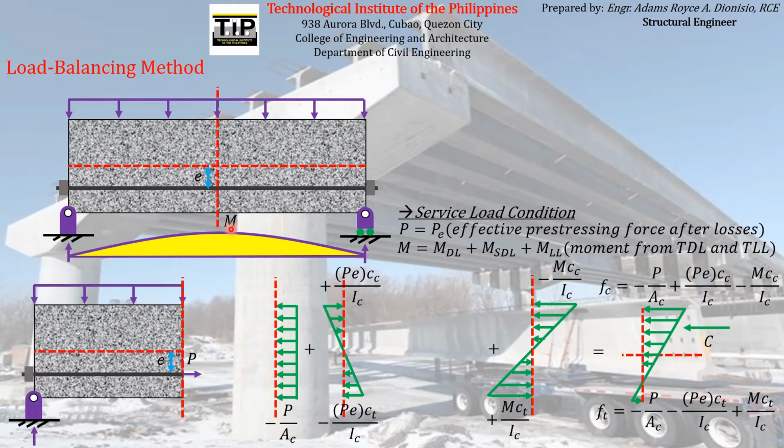This bending moment you see here is the maximum moment acting on the concrete element, which is the moment due to the combined effect of the dead load, superimposed dead load, and live load. So that is the variation of the bending moment that occurs inside a concrete element as it supports the total service loads, the dead load, live load, and the superimposed dead load.